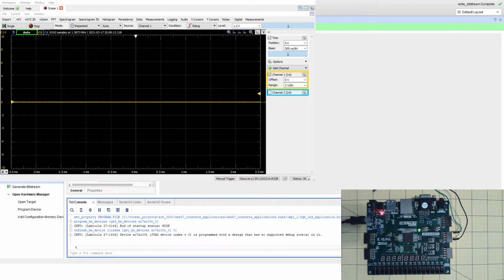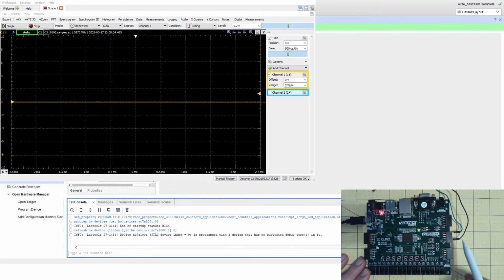So I went ahead and uploaded that bit stream to it, and now it's on the board. So the switches here, the first 9 switches from 0 all the way to 8, control the intensity of one of the colors, either the red, the green, or the blue. And then I can select which one I want using these 2 switches in here. So they're currently at 0, 0. That means it's red. And I went ahead and connected this here. As you can see, that here is what I can see, and it's now at 0, and then it is at 0.